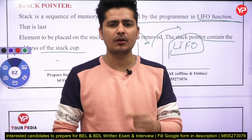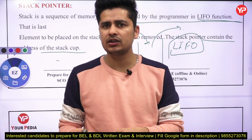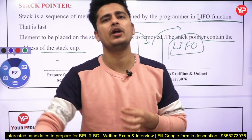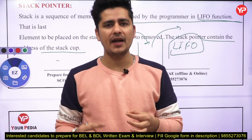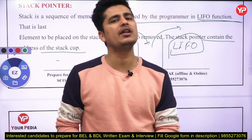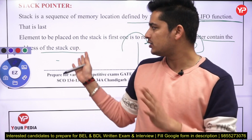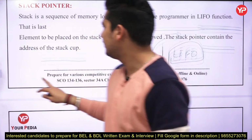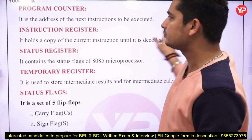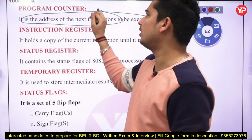Whenever you are performing any jump instruction, it will store the location of the program you are running, then go to the next one, and whenever it comes back and starts performing the same operation, it retrieves that information from the stack pointer. That is the use of the stack pointer in the 8085. Then the program counter: the address of the next instruction to be executed is stored in the program counter.